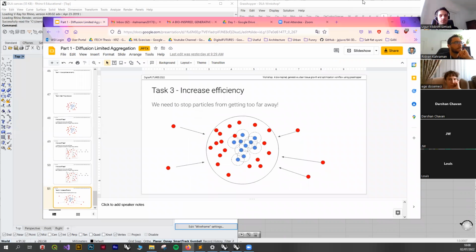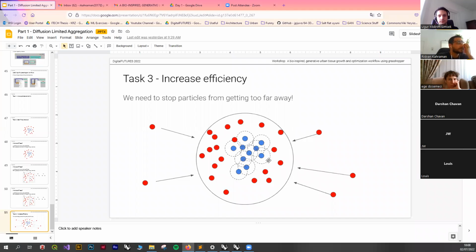the slides. So the idea behind this is basically we're going to define a big circle, and we're going to say every time one of these particles moves outside the circle, they're going to be pulled back to the circle, and then they're going to keep moving. It's not going to make sure that they go back inside. Maybe they will keep trying to go outside, but it's random. So it's better that they do a random walk here rather than all the way out here. So it's like a small trick that's going to make the simulation a little bit faster.